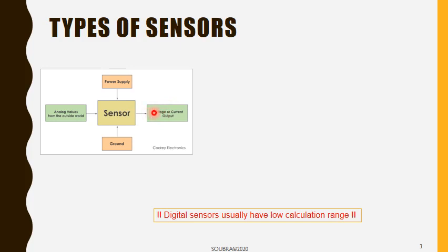So it's always a bunch of ones and zeros, or even sometimes the current, but it doesn't really matter. What I'm trying to say is, for instance, if you're using a temperature sensor, it's not going to spit out directly the temperature as you know it in Celsius or Fahrenheit. Rather, it's going to send voltages, and then you need to apply some kind of equations in order to get the equivalent of the information provided by the sensor in Celsius, Fahrenheit, Kelvin, or whatever.